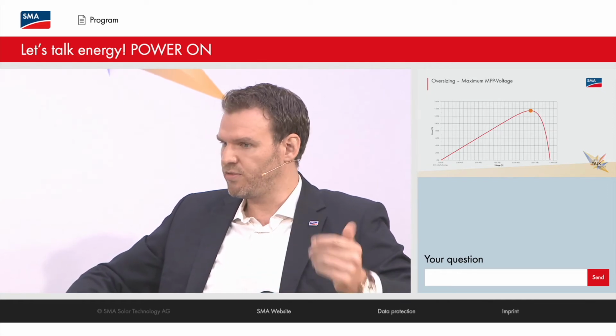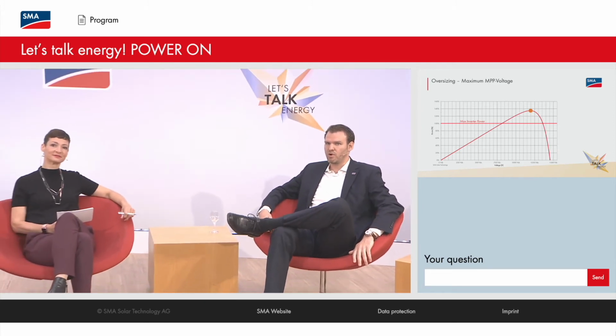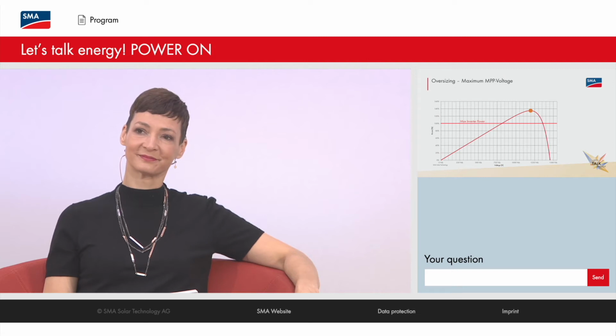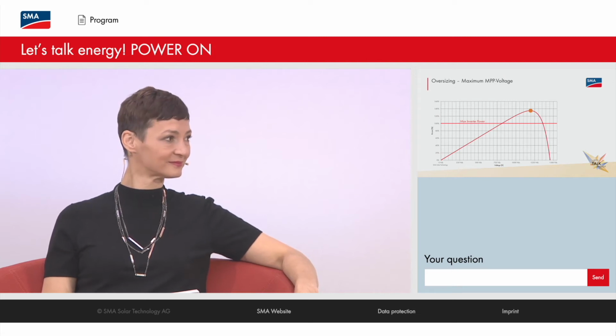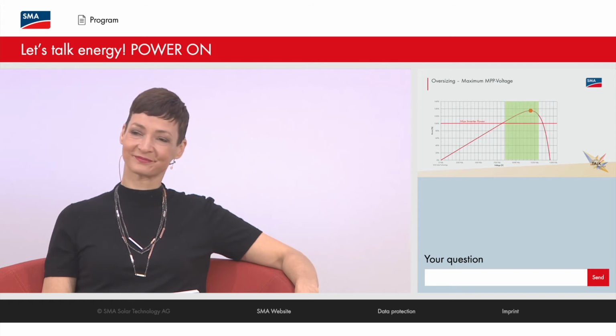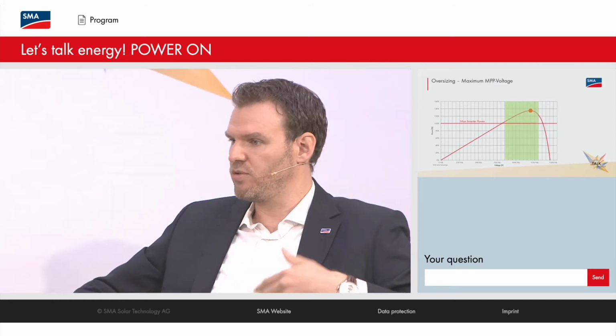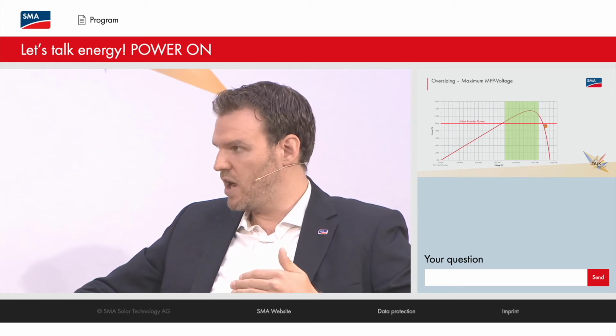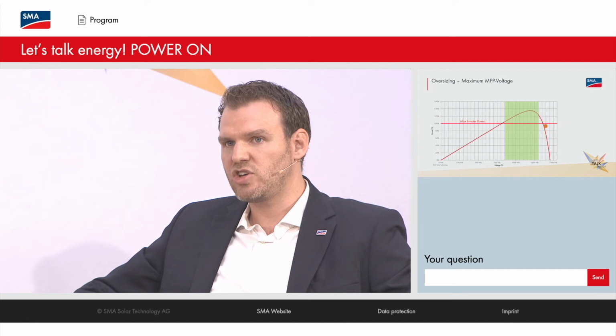And I think Jürgen in the first session mentioned that we plan with design reserves. And this is, I think, a very good example to look at in more detail. So this is the actual power versus voltage curve of a PV array. And usually you would be operating at that orange point. But since you are above the actual inverter rating, there will be some kind of curtailment. And the inverter is not burning this energy inside. It's actually reducing the output of the PV array. So it's actually shifting that operating point towards higher DC voltages.